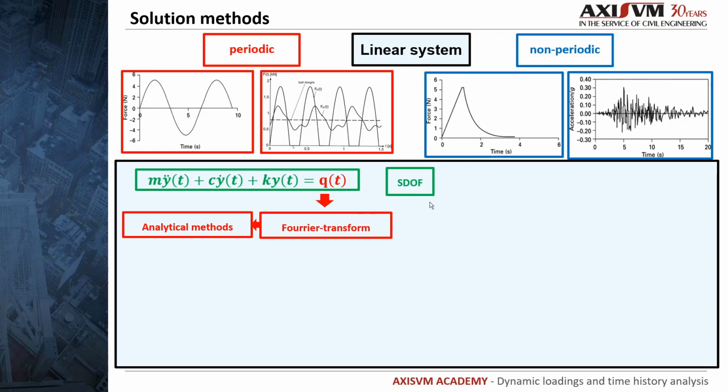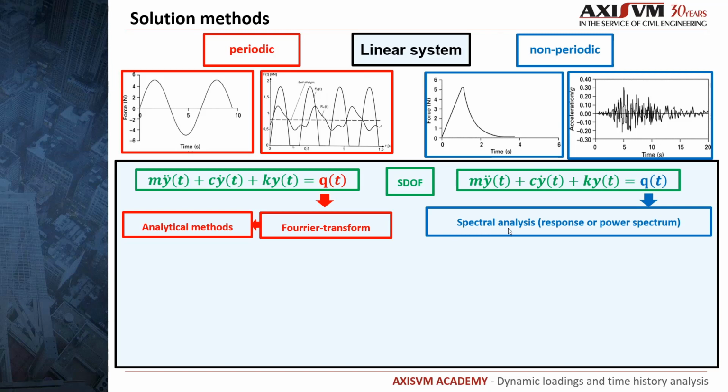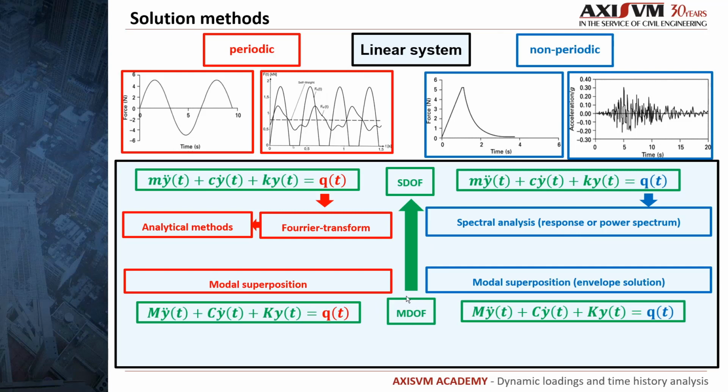In case of non-periodic loads, such as an earthquake, spectral analysis is often used to determine the response of an SDOF system. Please note that the spectrum shows the maximal responses of an SDOF system calculated earlier with time integration methods. The analytical and spectral analysis of linear MDOF systems utilize superposition to decompose the MDOF system into separate SDOF systems.